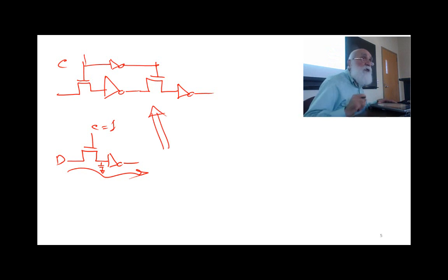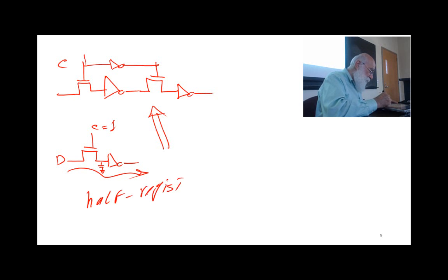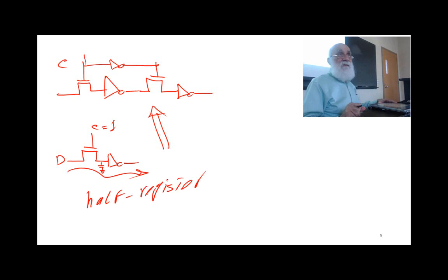In this case, I am putting two latches together. Oh, by the way, this is called half register. In the upper diagram, I'm putting two of these half registers together with complementary clock. Well, that's the same exact thing we did with the latches for master-slave flip-flops to build the master-slave D-type flip-flop, right? That's exactly what we did there.